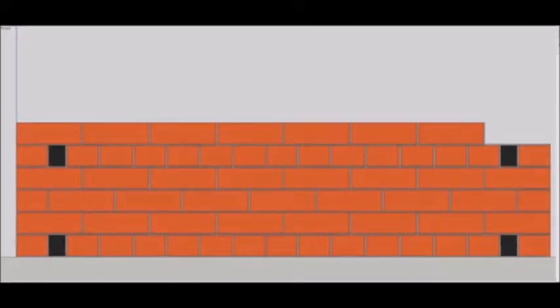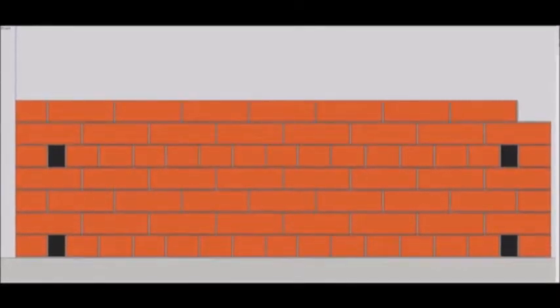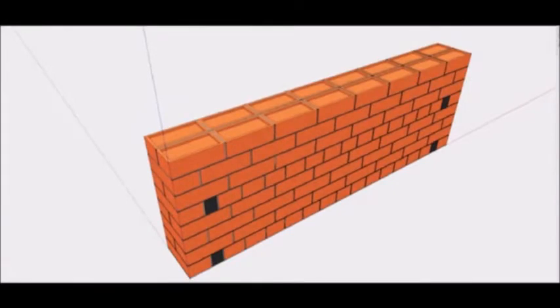For the standard English garden wall bond, headers are used as quoins for the middle stretching course, in order to generate the lap, with queen closers as the penultimate brick, at either end of the heading courses. The heading course in English garden wall bonds sometimes features bricks of a different color to its surrounding stretchers. In English chalk districts, flint is substituted for the stretchers, and the headers constitute a lacing course.